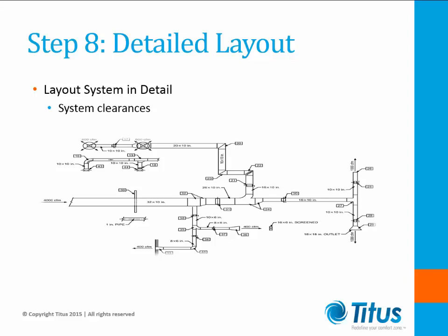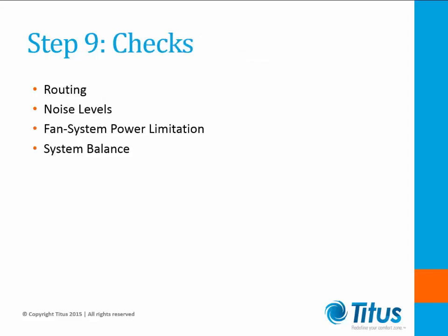Another method for transferring over limited height areas is to utilize multiple duct runs. Examples are given on Table 7 of the ASHRAE Fundamentals 2013, Chapter 21. Step 9. Checks. At this point, you should review the routing versus the original schematic and duct sizing calculations. If the system varies, modify calculations to match the new layout.